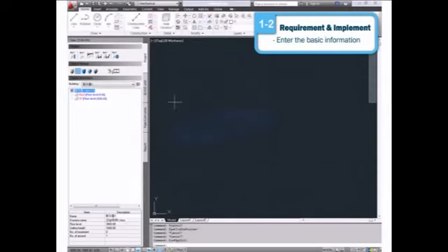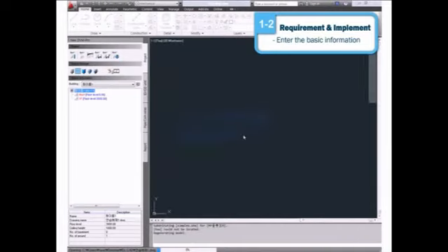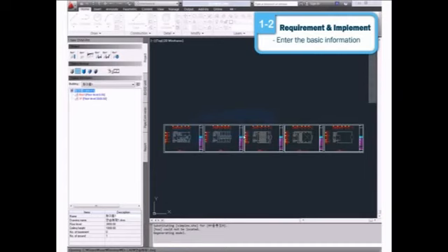Click the second assignment icon on the Zone Management section to open the drawing of the building. Click the sixth Process to Grayscale icon on the Zone Management section to lock the layer, and prevent the drawing from being edited. Architectural drawing in gray color is not editable.